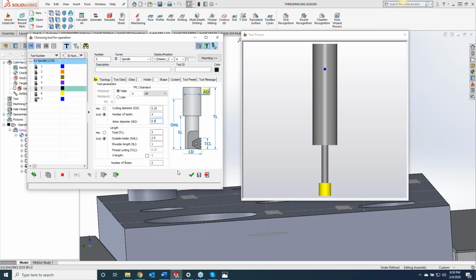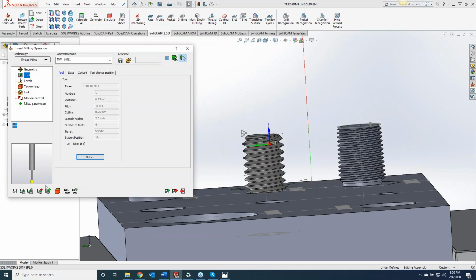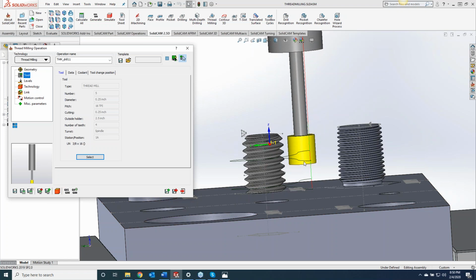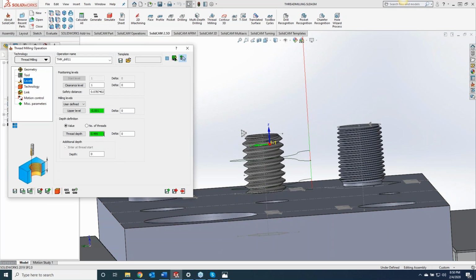So now instead of that 11. Yep. So if we go down to 4 teeth, that brings our cutting length down to 1/4 inch. And now if we do save and calculate, it's going to do it in 2 passes versus 1 pass, because we have a total length that we're cutting as 499.